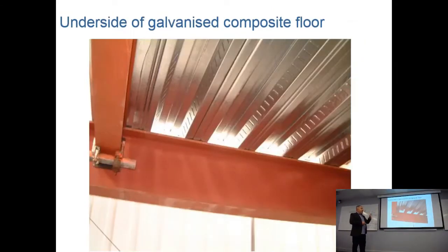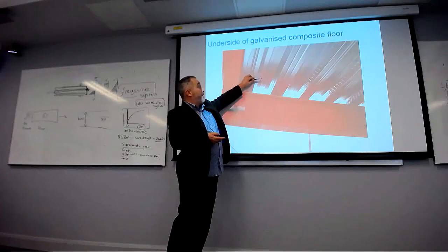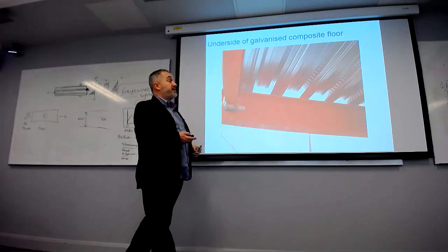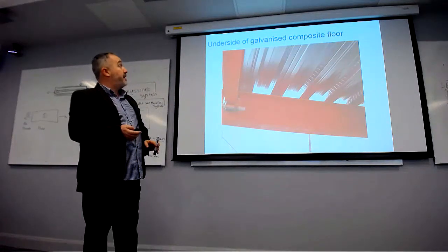That's the underneath of the wriggly tin. In terms of when you protect beams from fire, your main beams normally have to be covered in that intumescent paint that we covered when we looked at steel. Because the concrete protects the wriggly tin, it doesn't have to be sprayed with intumescent paint.